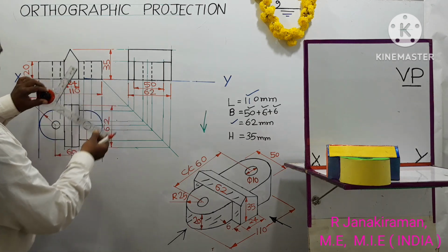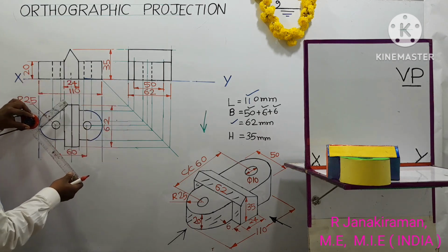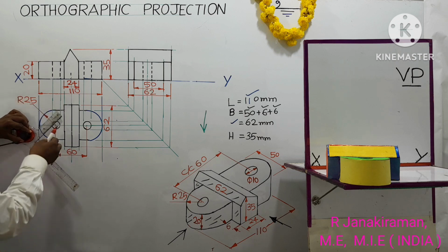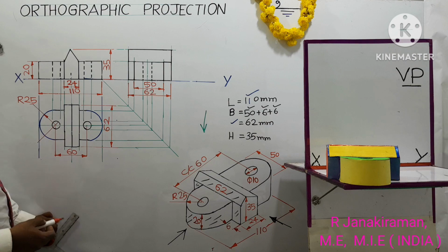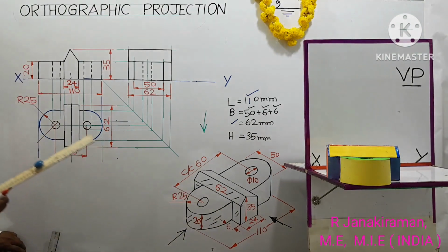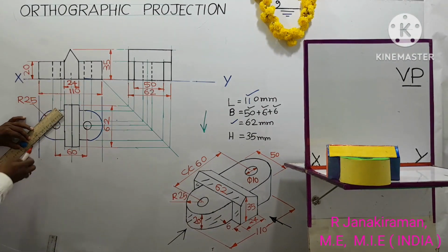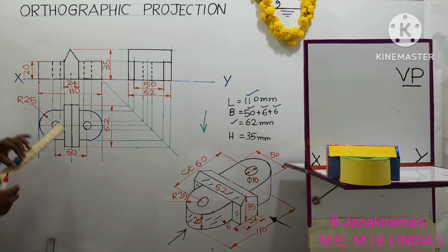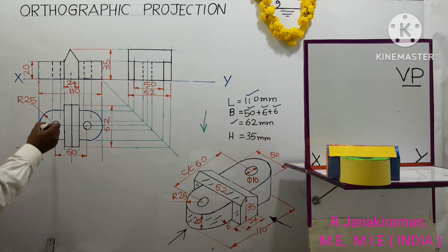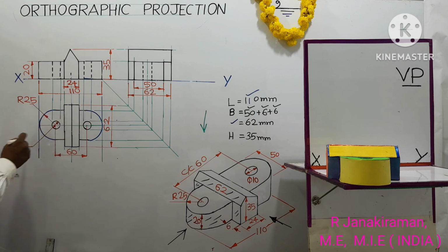Release your drafter scale, set it to 45 degree. Draw leader line, incline at 45 degree to mark the radius or diameter of the circle. Then you draw one horizontal line. This can be done by drafter scale itself. Provide 2 narrow arrows. If it is more congested, you can provide outside arrows also. Here I provide inside arrows for this 10 mm.